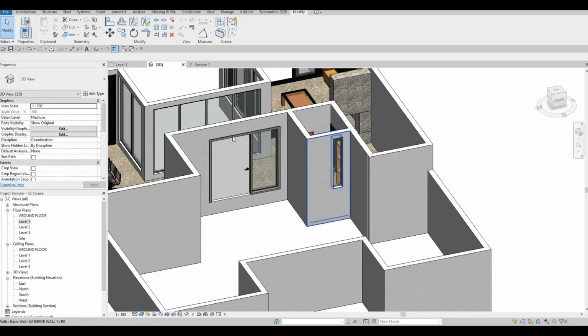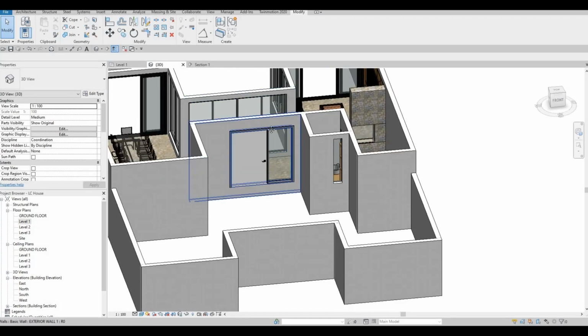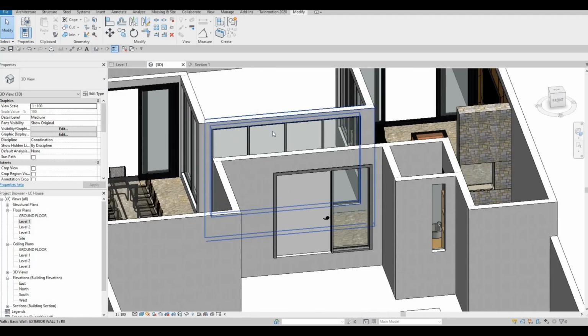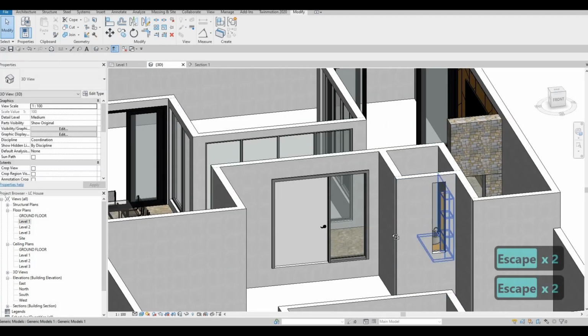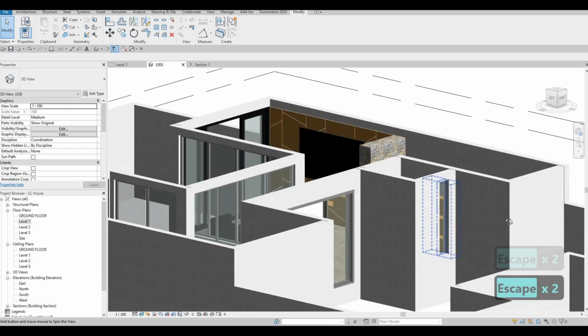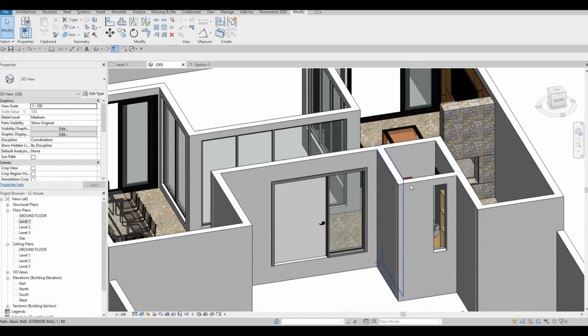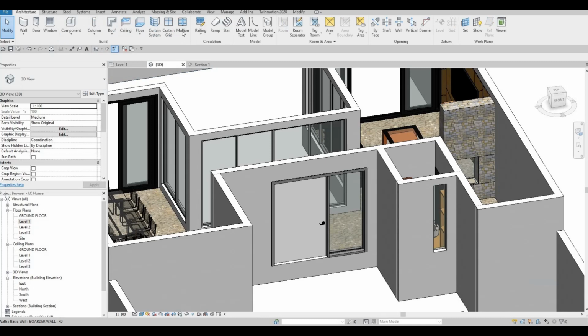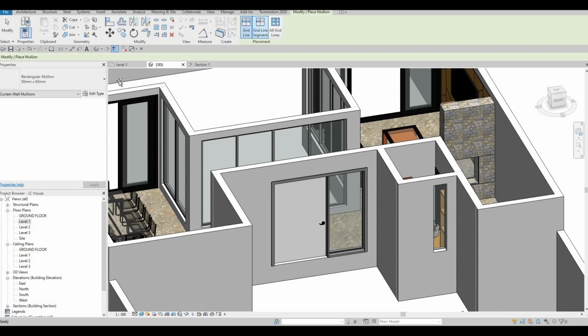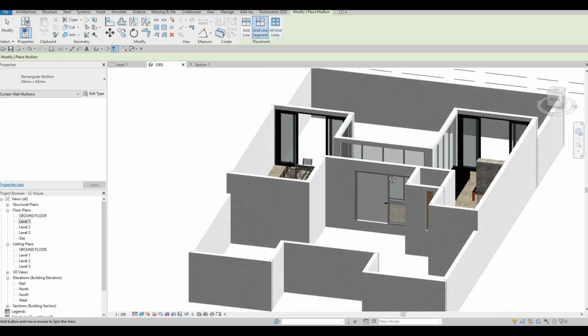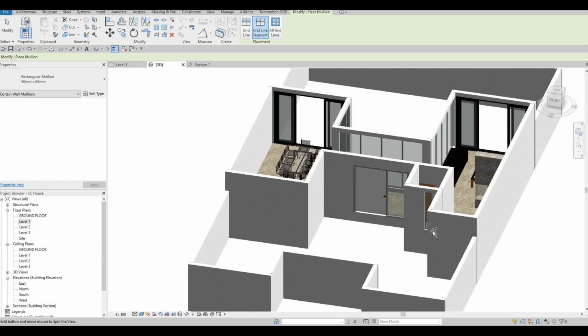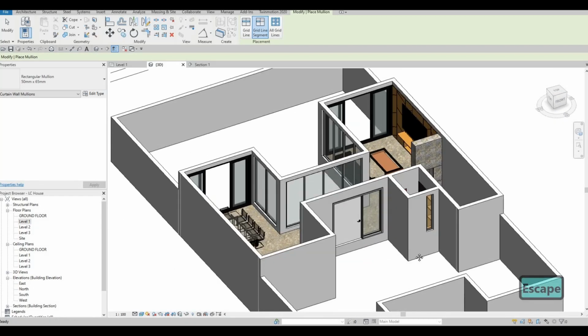And I always like to have everything that is consistent with height. So here, I'm going to align it from the top here and then align it right there. So that's perfect, same height, and then we have the width right there. So at least it's all the way at the top as well. And then now we just need to add a mullion and then all grid and then make sure this is 50 by 65. So let's click that, and that looks really nice, and that's good enough for that space.